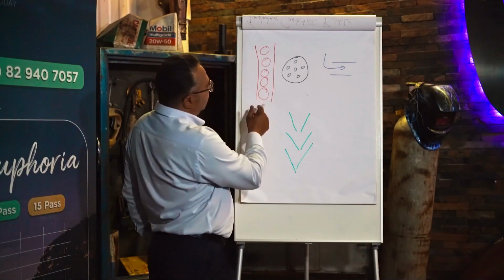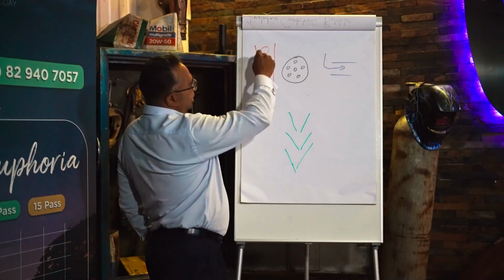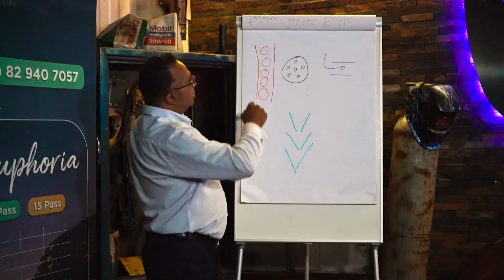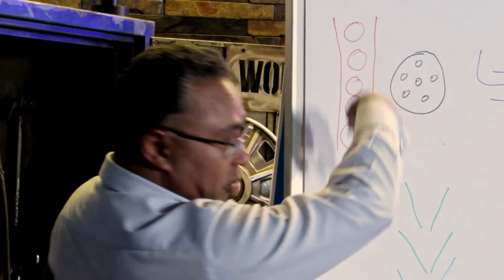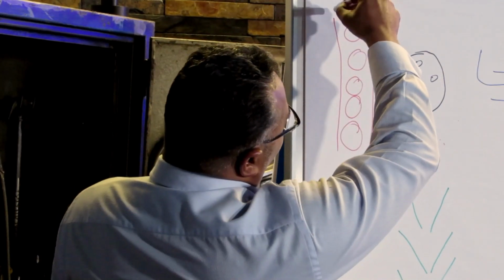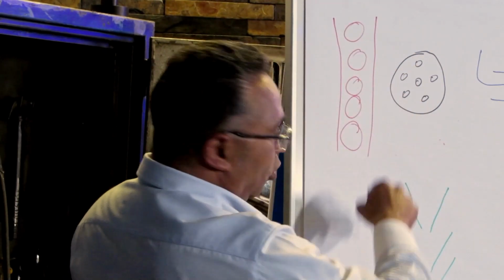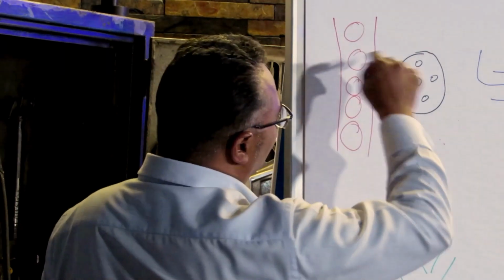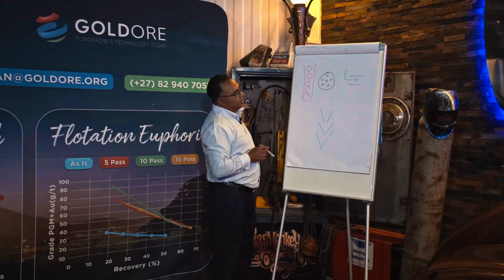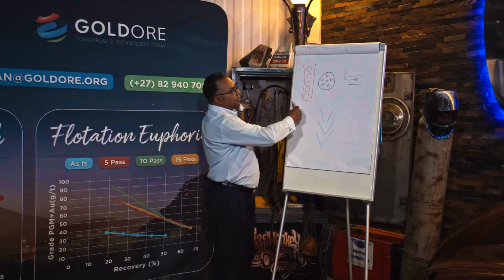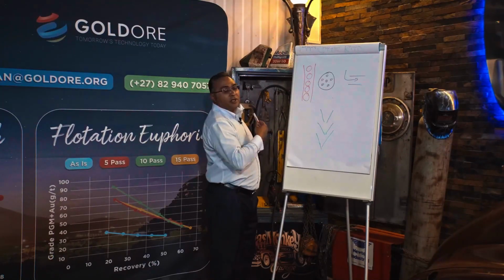And then on the other side of the shear reactors, you get the reactors that have the meander system, where you're pumping in through, you can imagine it as a pipe with steel balls in there. So the pulp has to move around those steel balls to get to the other side, and we create a bit of mixing, eddy formation, etc. in that manner.